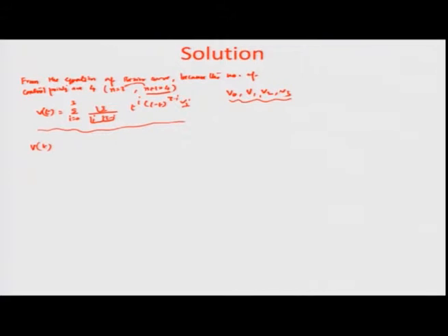So, I varies in that manner, and if I wanted to write this in algebraic form, this V of t would look something like V 0 times (1 minus t) whole cube plus 3 V 1 t times (1 minus t) square plus 3 V 2 t square times (1 minus t), plus V 3 t cube. I am sorry, this is not 3 V 3, but just V 3 t cube. T of course varies between 0 and 1, that is how the parametric form of the equation is defined. And we now start substituting the different values. You know that there are different x, y and z coordinates in case of these values.